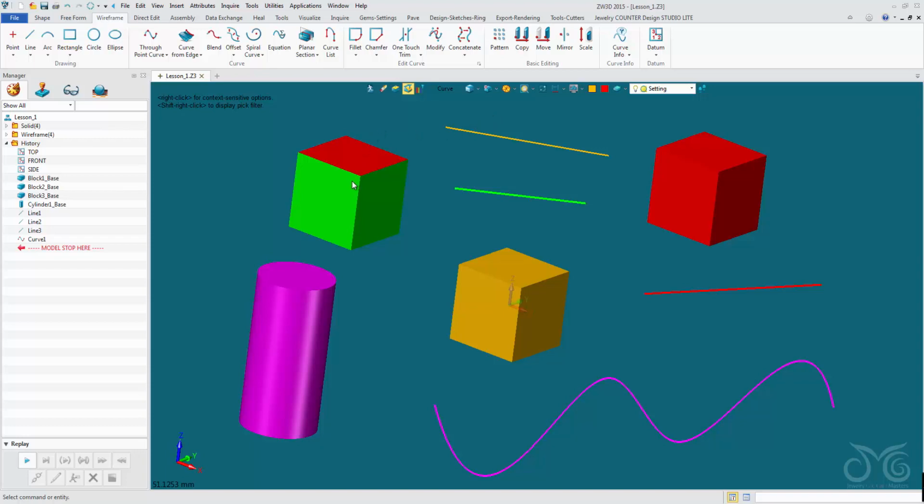Left click, and we can no longer see the black lines that define our edges. They are currently hidden in shaded mode. Left click to display edges in shaded mode. This one here says that we have removed hidden lines. If we left click, it will display the hidden lines. These are all of our lines that would otherwise be hidden by surfaces. So here we can see our edges and our datums. This also allows us to pick these edges through the surfaces.